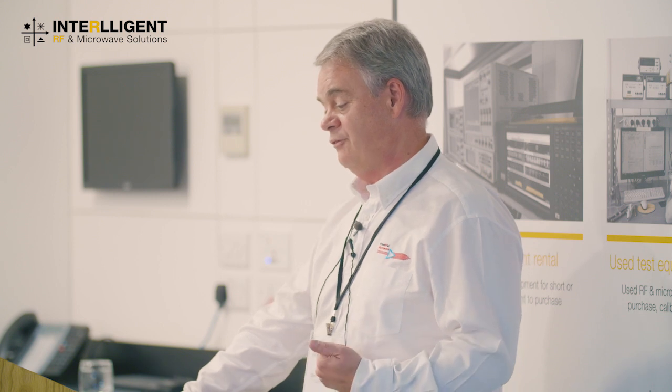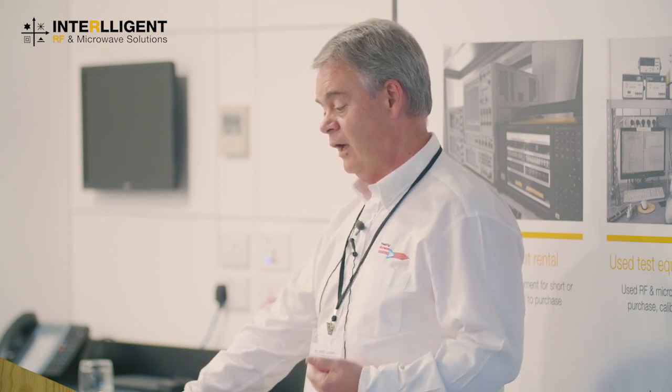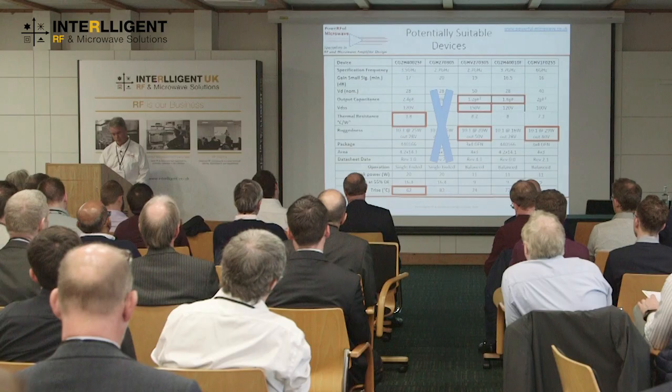It's also worth remembering that for single-ended devices, there's going to be an awful lot of gain that we're going to have to lose somehow. And we can do that with feedback, but otherwise your single-ended design is going to end with a very poor match on the input at the low frequencies. Whereas if you go for a balanced design, all the power that's reflected back from the input of the device goes into the termination of the first hybrid. So there is another attraction to going for that type of topology.